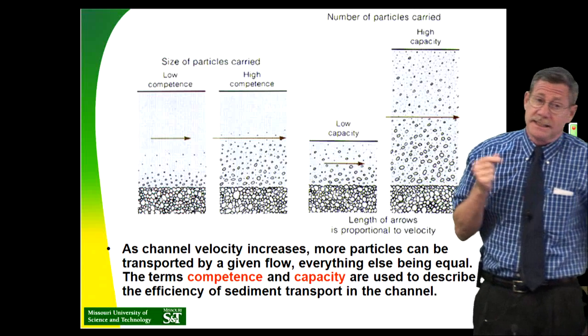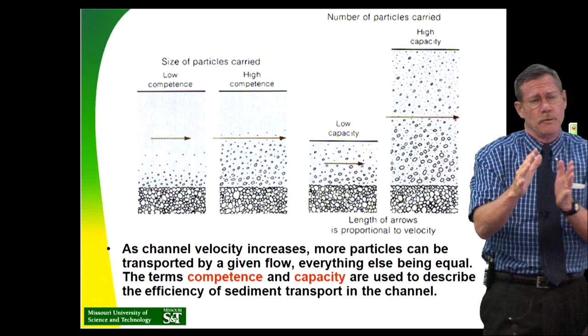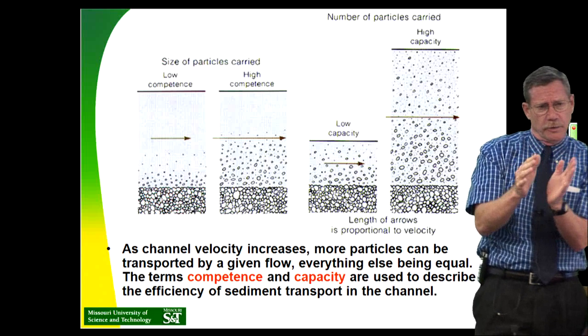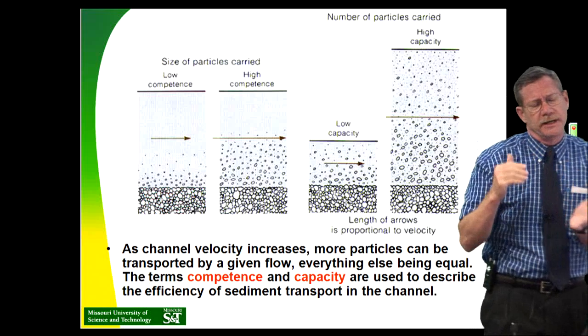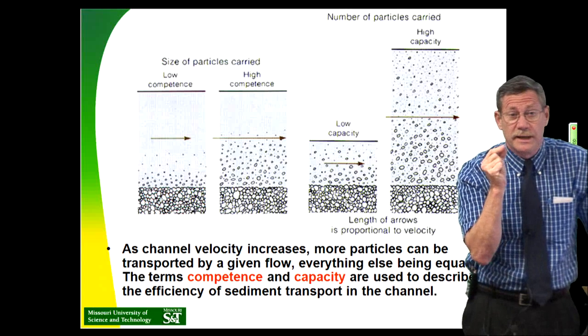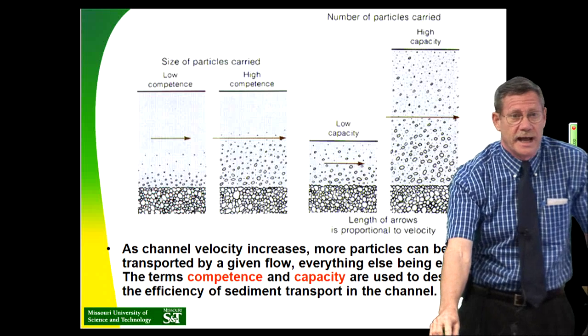That's tough to do unless you have something really rough like gabions, and then when you put the gabion wall in, it's got to be really tight and match the profile of the bank upstream and downstream, or it's not going to work real well. Those things take a lot of finesse, construction-wise and design-wise, to make them happen. So they don't happen very often.